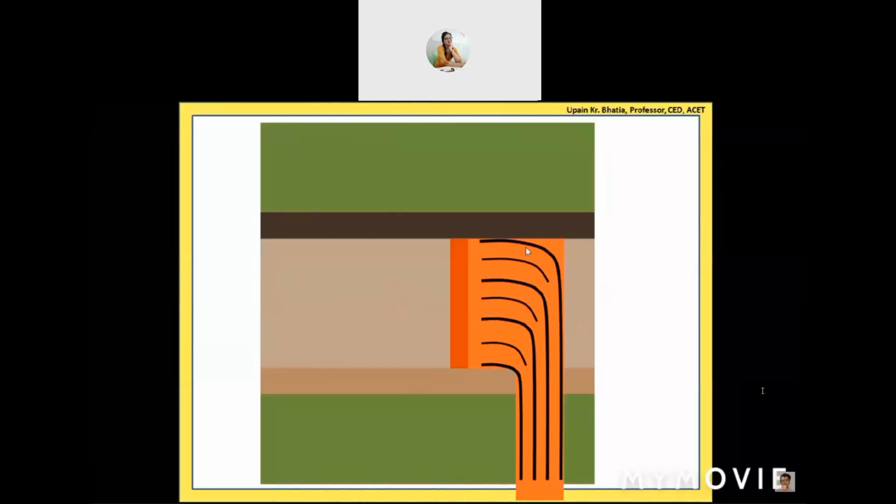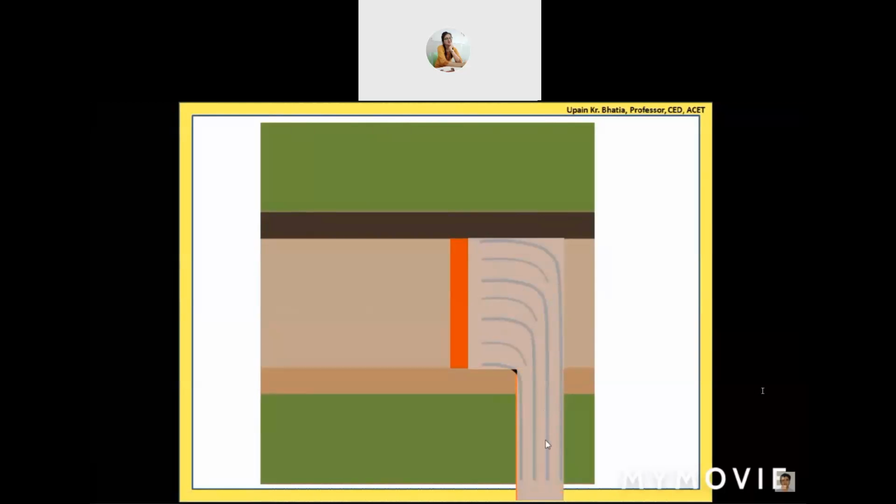The top level of all these walls is at the same level, and that is a little above the canal bed level. Thereafter, we cover it with a concrete slab. A very thin diaphragm slab is provided on the top. It is covered on the top side. But you see here, we have not provided any slab, so the water in the bottom layer has a passage in this portion to move underside of this slab and go into these tunnels. Here also, we provide this concrete slab.